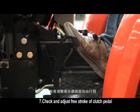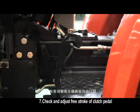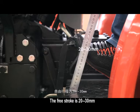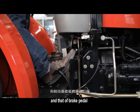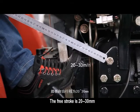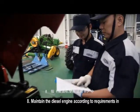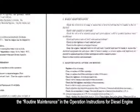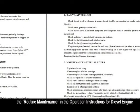7. Check and adjust the free stroke of the clutch pedal. The free stroke is 20-30 mm, and that of the brake pedal, the free stroke is 20-30 mm. 8. Maintain the diesel engine according to requirements in the routine maintenance in the operation instructions for the diesel engine.